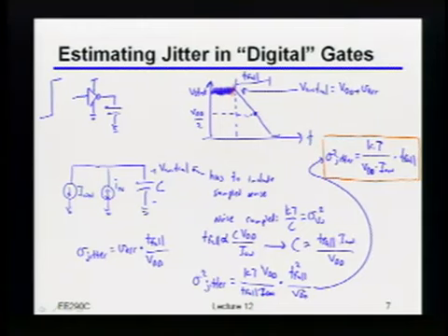So if I've sampled that wiggle, then even if I don't have any noise while I'm pulling down, just because I started from some slightly unknown position, that's also going to translate into an error in terms of when I actually make the edge crossing at the output. So we quickly went through how you would derive something like that. By the way, for this part, we're really just focusing on the jitter due to that timing uncertainty, or rather the initial voltage uncertainty.